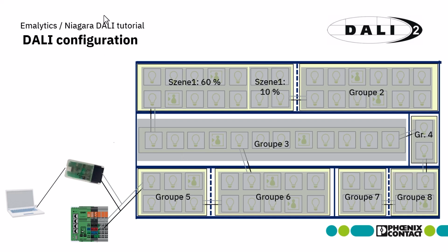Because it is like that, we can choose the configuration tool we already know and worked in, if we want. So here's an example. We can just connect a DALI mouse to our DALI line, so the DALI power is already implemented here, and we can connect our notebook to any kind of configuration tool and do the configuration as we know it since years.